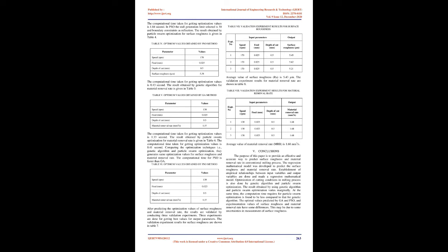Optimum results of cutting conditions are obtained by comparison of values of objective functions among all individuals after a number of iterations. Particle swarm optimization, PSO, is a population-based stochastic optimization technique, inspired by the social behavior of bird flocking or fish schooling. A population of individuals defined as random guesses of the problem solution is initialized. These individuals are also known as particles, hence the name particle swarm. The value of the objective function for these individuals represents their positions. An iterative process to improve these positions is then started.